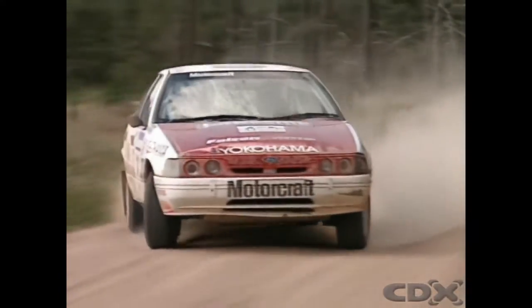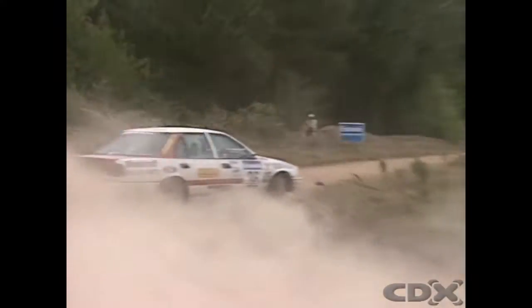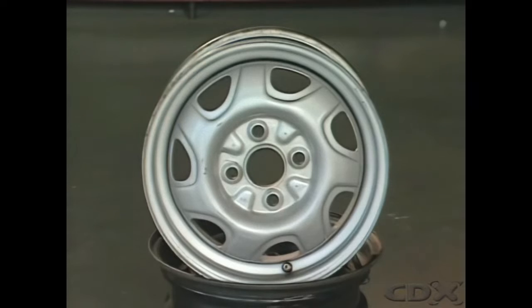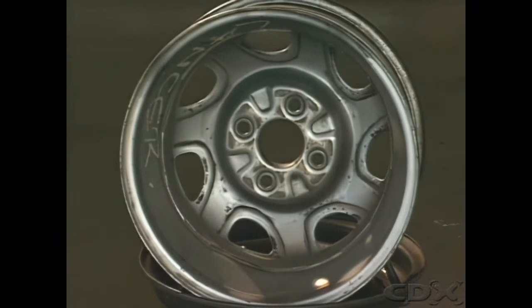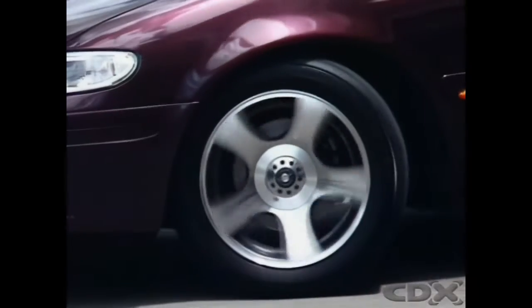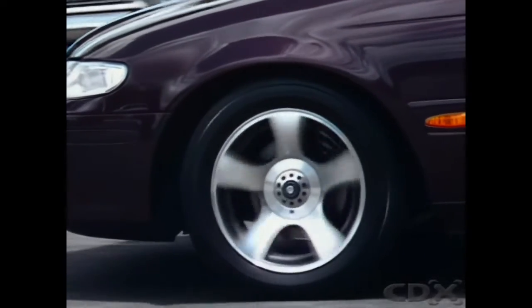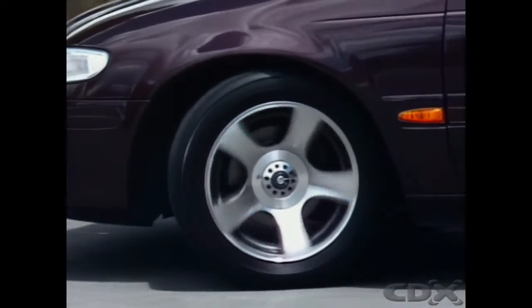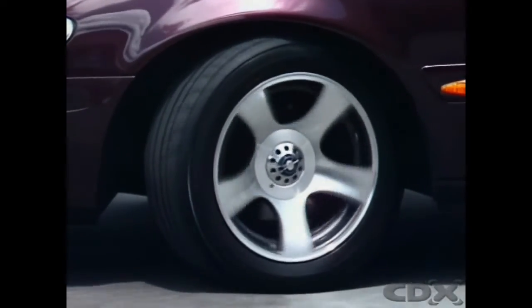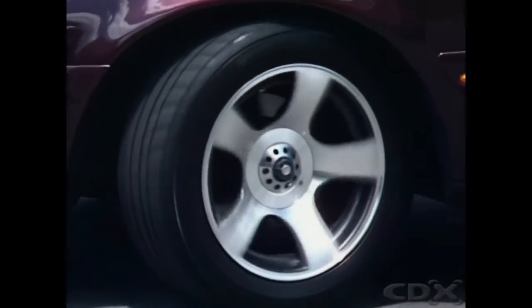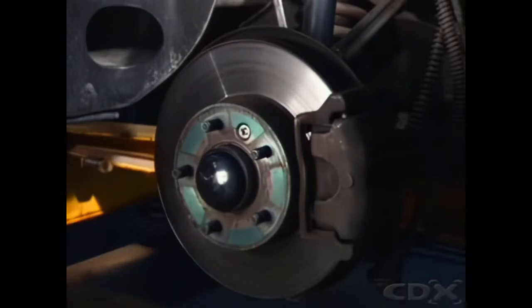Wheels must be strong enough to carry the mass of the vehicle and withstand the forces that are generated during use. Some are made from steel. They're pressed in two sections, the wheel centre with a flange or disc that's drilled for the wheel fasteners, and the rim. They're then welded together. Others are made from cast aluminum alloy. Alloy wheels are lighter than similar steel wheels, and since aluminum is a better heat conductor than steel, alloy wheels dissipate heat from brakes and tyres more quickly than steel wheels.